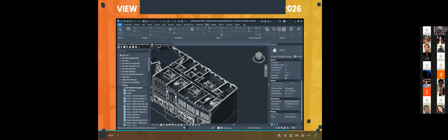And then there should be another template that I pull up where I remove the walls, as we discussed that one of the purposes of view templates is to enable better coordination and also to turn on and off sections of the drawing that you would want to see and what you wouldn't want to see. So it was overall demonstrating everything that you can do with view templates in a simple manner.